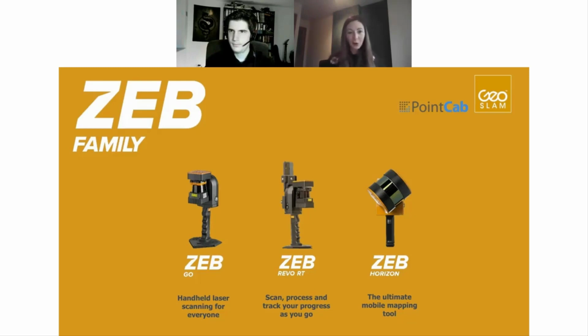introduce the ZEB family. ZEB Go, Revo RT, and Horizon are the core products, where ZEB Go is the first step into handheld scanning. It's the most affordable one, and it's got a range of 30 meters. Similar to ZEB Revo RT, it's got the same range. RT stands for real time, so you can actually see the data as it's being captured, which is a great advantage in very complex buildings, but the data is also processed in real time. Both systems capture 43,000 points per second, have a 30-meter range, and are really great for indoor mapping.